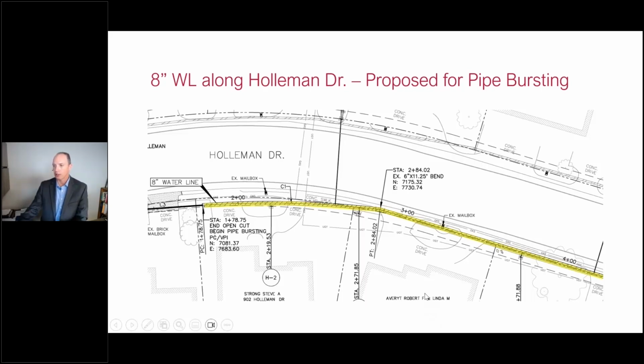But when the contractor got out there and started doing some investigations, he discovered that there was an existing 4-inch gas line that was a little too close for comfort. We did identify this in our design, and based upon the record information that we had, we thought that we had 3 to 4 feet of clearance from the water line for the majority of the way.